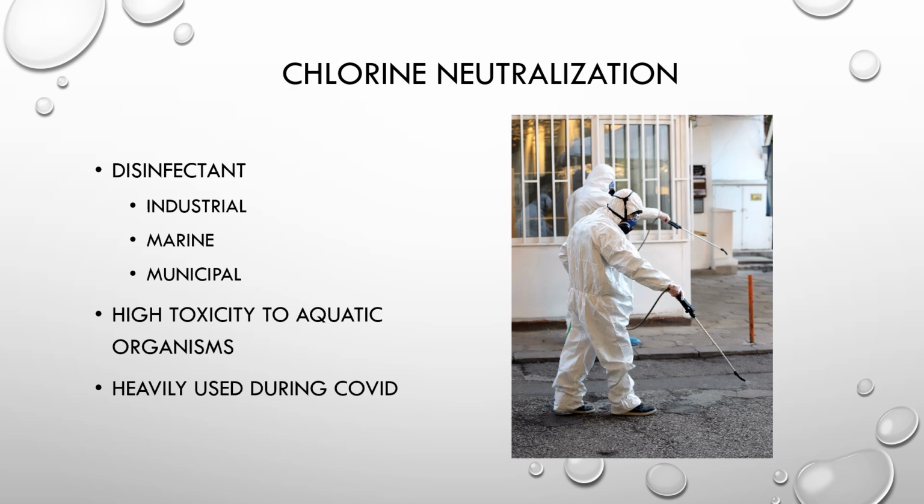And then the final piece was chlorine neutralization. Again, just like with the pH log, anionic PAM is not going to neutralize or affect chlorine really in any way. But we use other low toxicity types of materials that are able to neutralize chlorine, and we use the polymer as a delivery system. We typically use this now for things like municipal swimming pools when they need to empty them and clean them out, things of that nature.